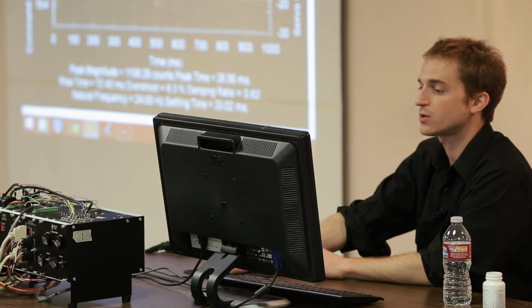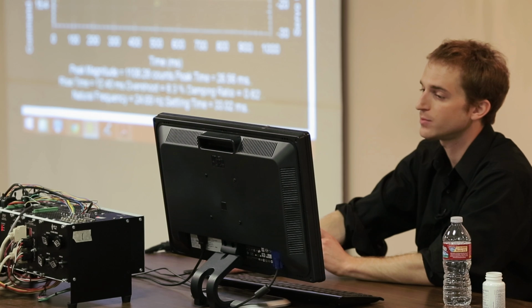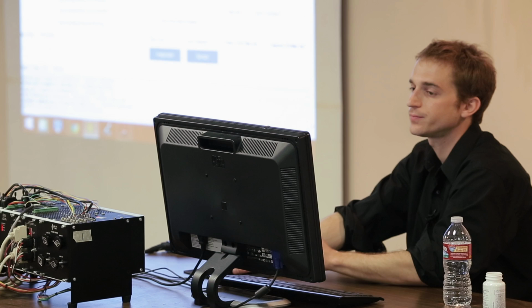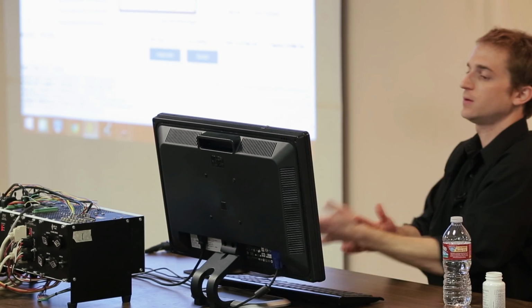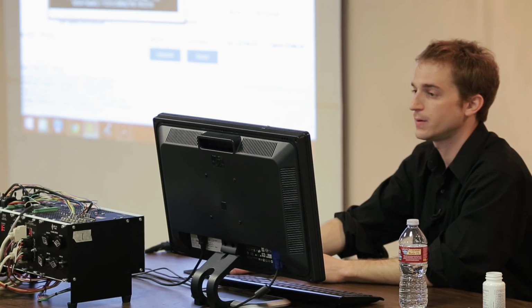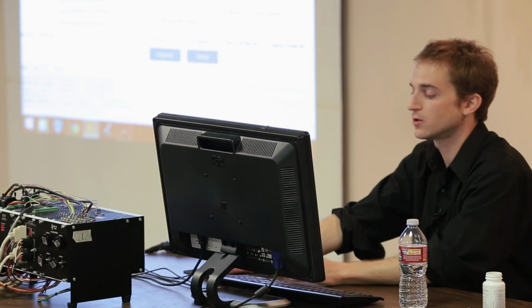Now that gap is almost totally gone, so I'll just keep increasing Kp until the gap between the resting actual position and the servo command is gone. Let's do a large jump. Now there's almost no gap, so just increase a little bit more.